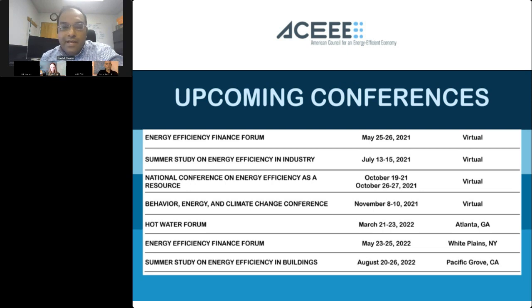We have done some analysis on that, and I can share that information, which basically looks at the fundamental properties of the phase change materials which you are considering: the density, the latent heat, and the heat capacity. And based on that, we can do a good assessment. Like if you are, let's say, exchanging 1 liter of hot water tank with that material, then how much additional capacity you're going to get due to that replacement. So yes, there has been some analysis, and I can share that information.